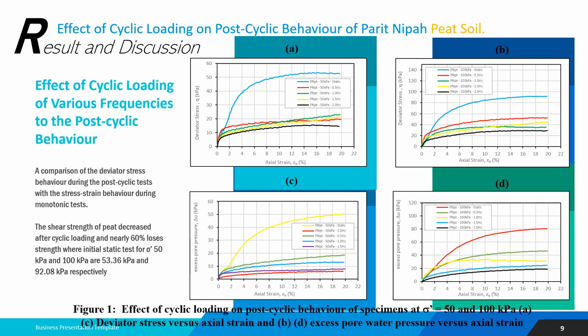different confinement pressures exhibited, in a cylindrical specimen under cyclic shear strain ranging between 0.3% and 1%, a growth in the damping ratio and a shear modulus degradation of 10% at the end of the first 5 cycles of each strain level.